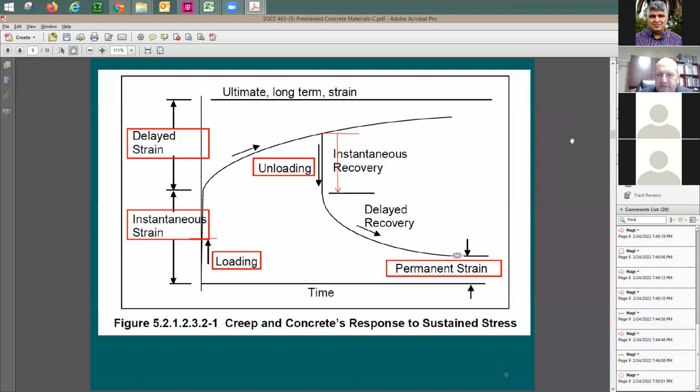Because this is not dynamic stresses, right? This is unlike seismic, and seismic is going to be completely different. It's going to be something that we call hysteretic performance of concrete. So all of that is going to be low cycle fatigue, and we call this quasi-static, as if you are applying just a static load. It looks like a static load, right?